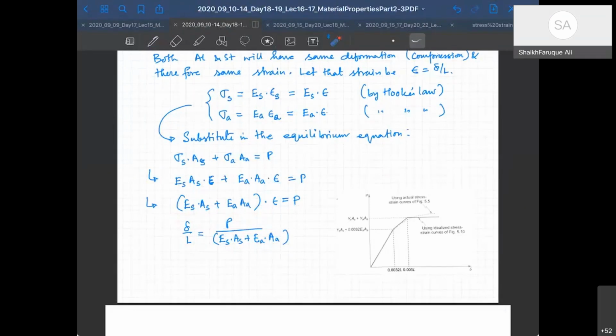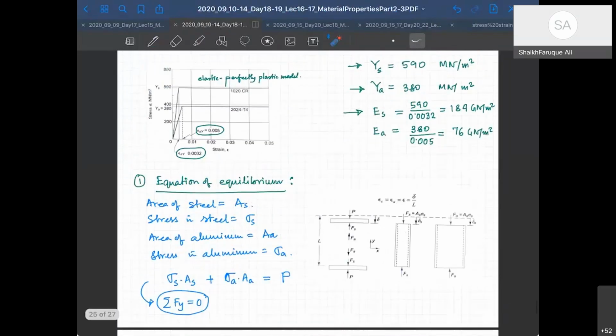The difference lies in whether the materials are connected in series or in parallel, like in electrical circuits, or like in springs. You have learned parallel springs and series springs. So here they look like a parallel spring because one spring like this, the other spring like this, and both undergo the same deformation, right? So the stiffnesses are added up.